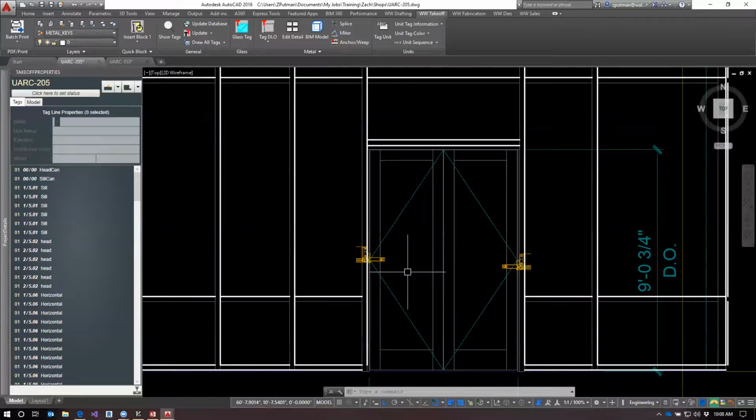You don't want to duplicate data very much. Taglines are easy to draw, and if this door changes height, maybe the drafter stretches this thing later on, you'll be completely fine because your tagline hopefully will get stretched, or at least you'll see that your tagline isn't as long or as short as it needs to be. It's just way more flexible if that pocket filler is a separate tag on this door and size to the door. Gotcha.